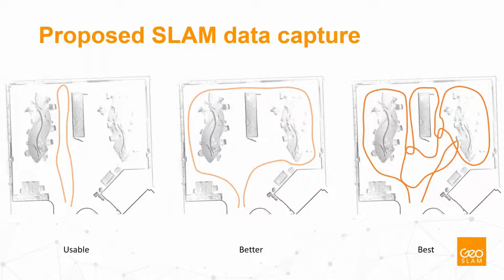This, however, doesn't mean that we cannot use our system for roads, tunnels, or power lines, scans and mapping that are linear in nature. It just requires a little bit more planning and making some smaller loops on the way. So in case of Revo or RT system, it's helpful to have smaller local loops, let's say every 30 meters in the linear capture, and around 150 meters for Horizon. You would select a group of several trees and loop around them within a diameter of around 10 meters.